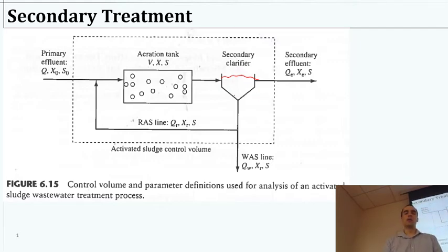We also want to make use of this sludge that's going to accumulate and recycle a portion of it so that we can keep the right bacteria and the right amount of bacteria happily growing in our aeration basin. So we need some sort of a seed stock to keep the process going. Ideally, this clarifier will work perfectly and it'll remove all the bacteria that we grew. We measure typically on a mass basis. I'll explain that in a minute.